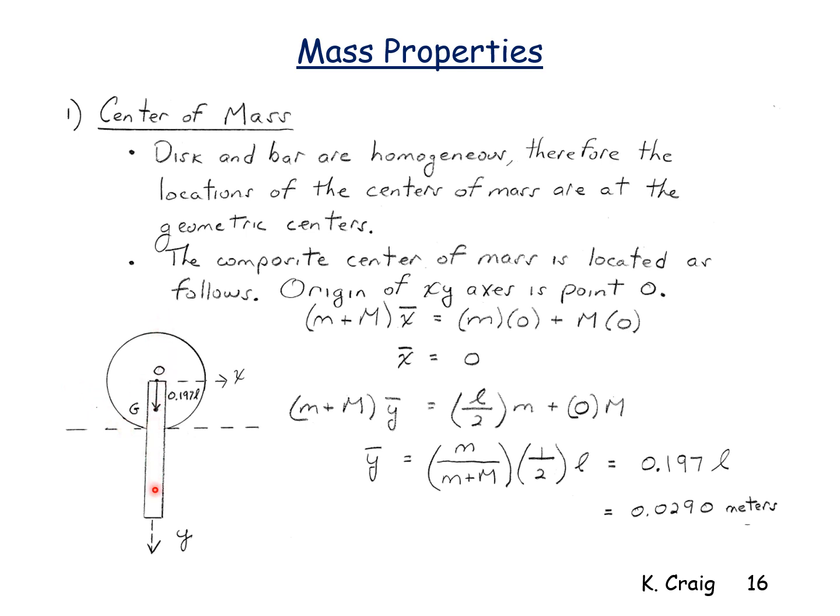So the center of mass has to be located on this Y-axis. Hence, X bar is equal to 0. My equation that locates the X coordinate of the center of mass is the total mass times the location of the X coordinate of the center of mass, and that equals the individual masses times the X coordinates of their individual centers of mass, which are 0.